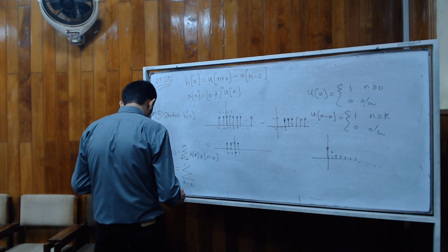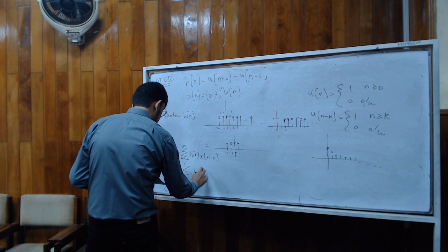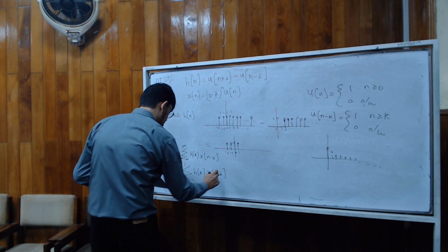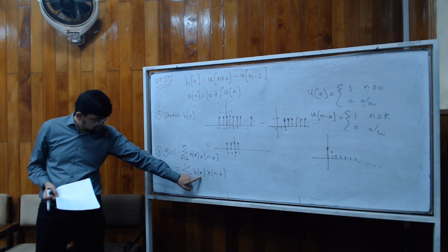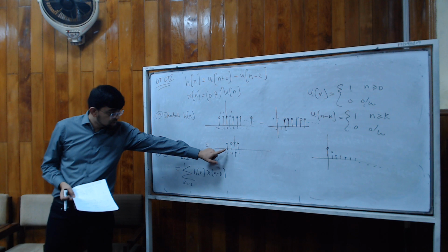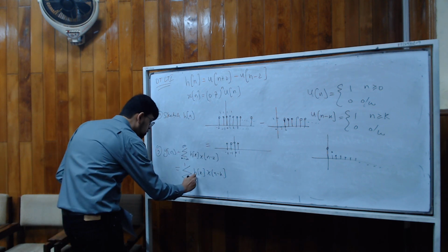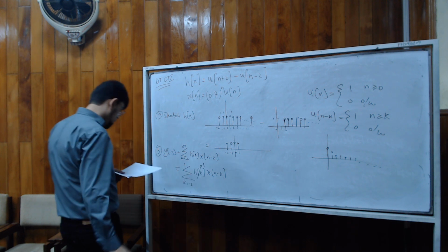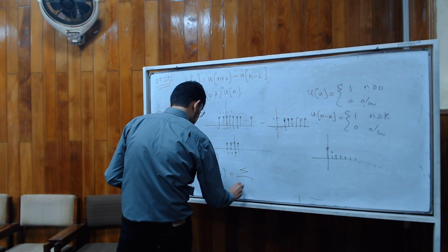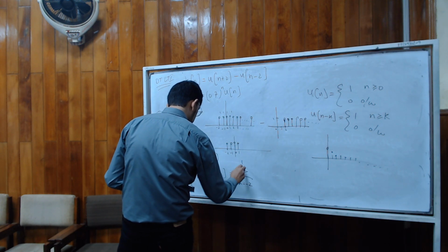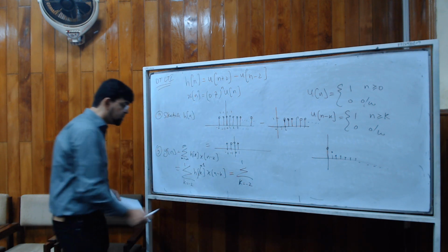And in that range, what do we know about h[k]? So h[-2], h[-1], h[0], h[1]. What are the values of h in this range? From here we know they are all ones. So you can simply replace this with ones. So that essentially means that the output is basically k equals -2 to 1, whatever the input is shifted by n minus k.